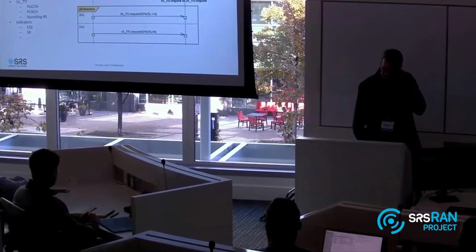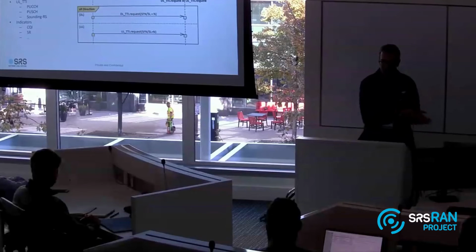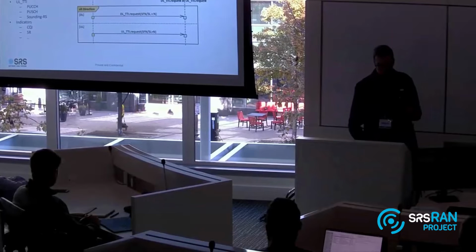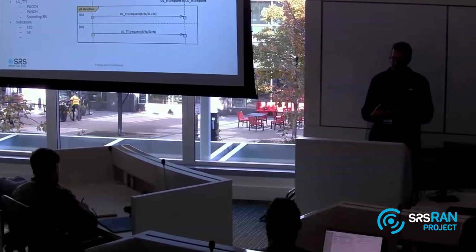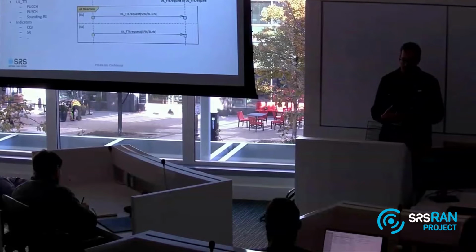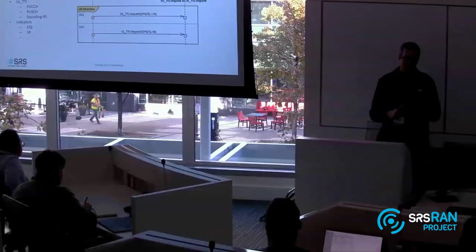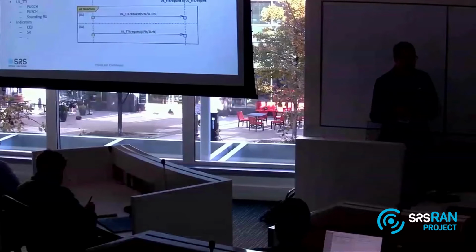The downlink TTI message, for instance, is what generates the PDCCH grants for both uplink and downlink. It also configures the SSB, and configures things like the demodulation reference signals, the CSI. So notice that from the point of view of the PHY, it is completely stateless and completely dumb, if you want.